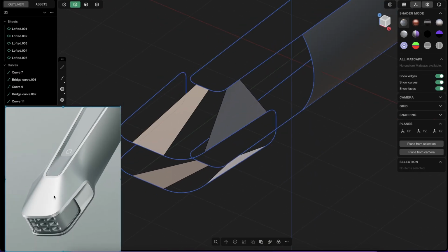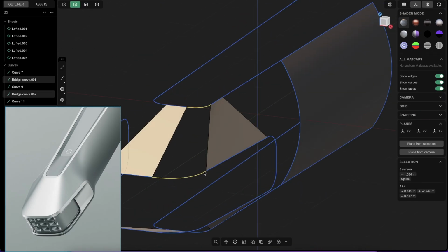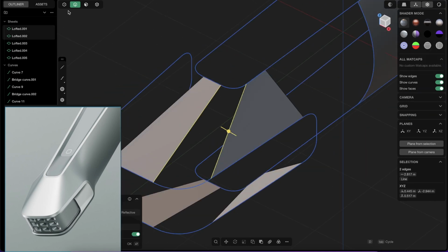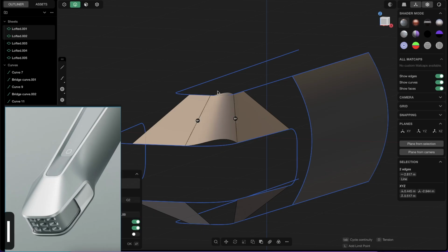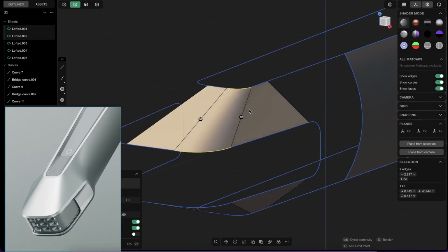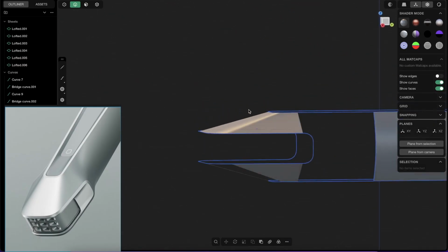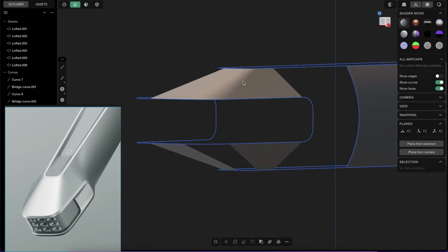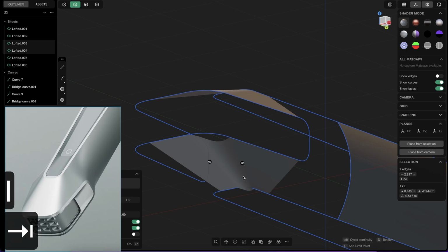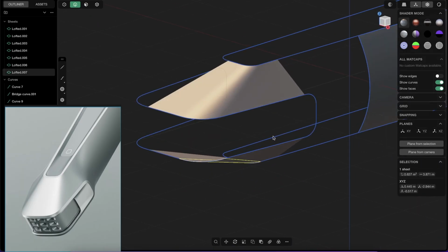You see it has like a very nice smooth rounding, and because our curves, as you remember, they were G2, so this bridge curve thing, we can give here, so if you select in edge mode those two edges, and if you press L for loft, you can press tab for G2 and shift, and you see guys, right click, and you see you have a very nice connection, and it works with G2. So the same here, loft, so shift, press tab, and shift, and the same here at the bottom.